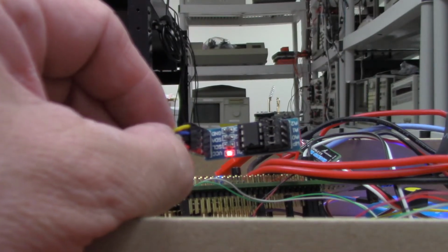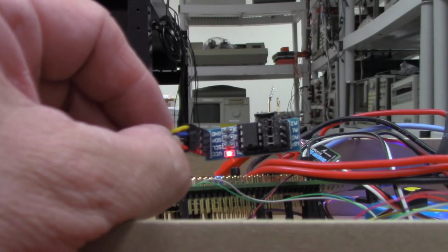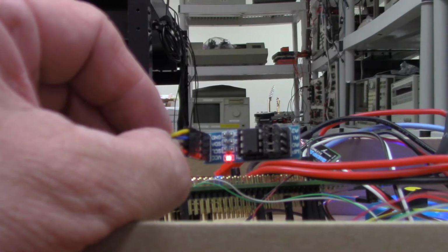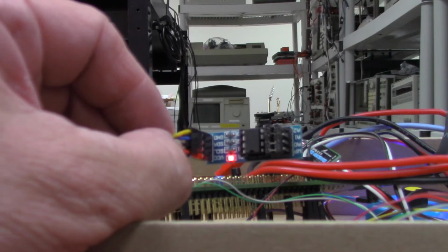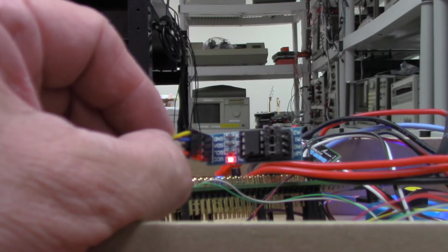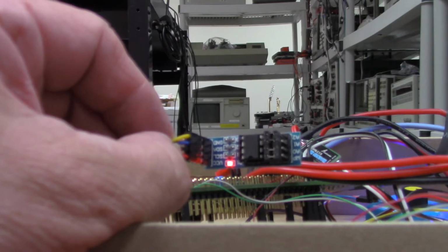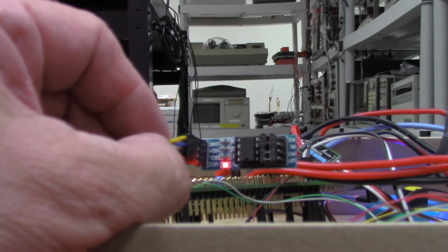So the next module I have here is called the AT24C256, and this is an I2C EEPROM where I could store non-volatile memory. This is just a little module. It also uses I2C, and we'll take a look at that. The demonstration I have here is that when it initializes, the memory addresses are set to 0, and then I change them to 1, 2, 3, 4, 5, 6, 7, 8. So they're 8-bit data, bytes that you could store.